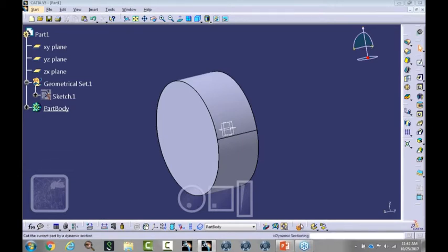Right here, if you watch down here, right below my cursor, I have C:, and let me do this one over here, C: instantiate from document. Instantiate from document is the name of the command. So if I go and sit on that scaling command, and again, look to the left, it's called the power input area. Look to the left of that, C: means command, and then the name of the command. So you can go through any workbench and see the names of all of the commands that might be of interest to you.